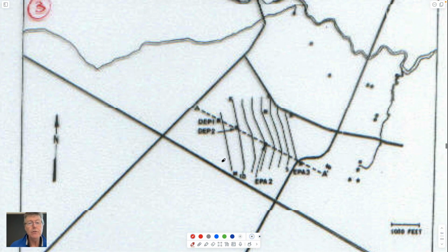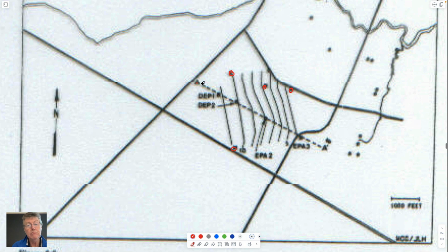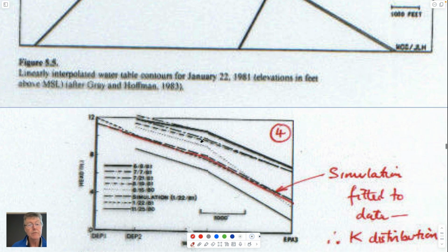And of course the behavior you have would be by looking at these individual boreholes, which would have, for instance, water pressures or water levels in them, which you could then draw a section through. And on that section you could plot how the water levels change as you go downstream. Flow obviously would be in this direction as you go from high head to low head along the section. You'd expect maybe that there's some heterogeneity in here, that you have this kink in the water table or something going on.